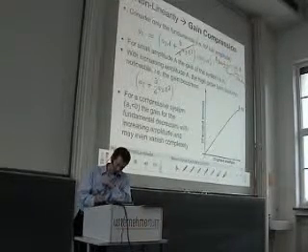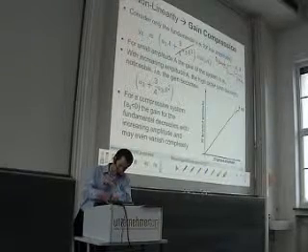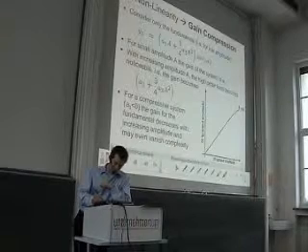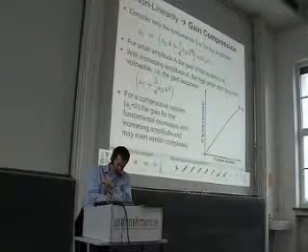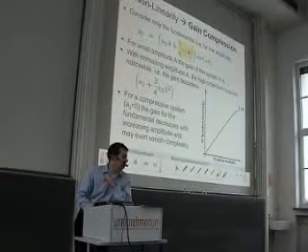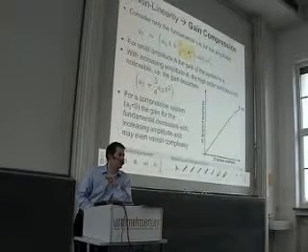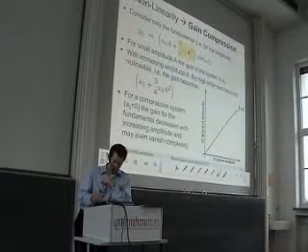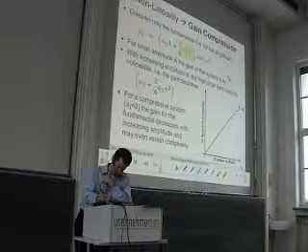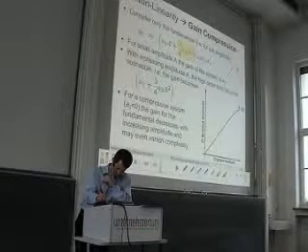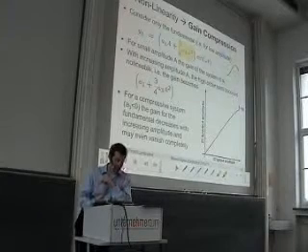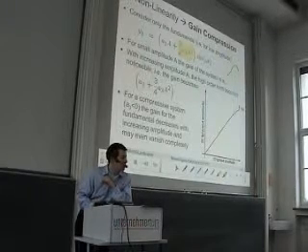However, this is not true if my amplitude is increased, because then I also have to take this term into account. Let's assume that a3 is negative, which is very often the case, which is the case always if I have this saturation type of characteristic that flattens out for large and small values. Then a3 is negative.